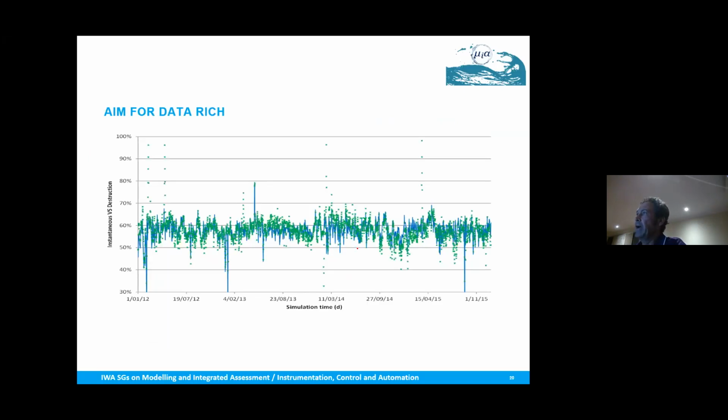Let's just talk about how you actually fit the data. Here you can see the ADM1 fitted to continuous data over about 3 years. This is from a full-scale reactor in Melbourne, Australia. The question they had for me was, what's our sludge characterization? Has our sludge characterization changed over time? So I did this process where I fit the degradable fraction, assuming a proportion into carbohydrate, proteins, lipids, as well as the speed, based on the volatile solids destruction. Those parameters are then fixed over these 3 years.